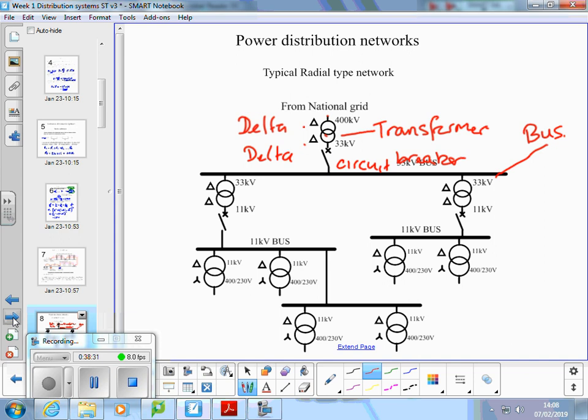It's like a big interconnection between a number of circuit components that's able to take a lot of current. So would normally be a big copper bar that all the circuit breakers can connect to. And these circuit breakers can stand this high, and they can be racked out and completely taken out of circuit. So they're huge great things.